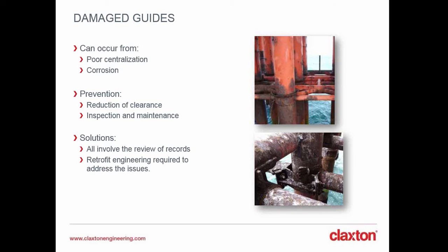So even if you try to minimize the overall ID, you might find yourself with a problem later on when it comes to designing a centralizer, because you will not have allowed sufficient space for a centralizer to be installed or a pre-installed centralizer to be run. So you just have to be a little bit careful with what you design, because you can also be limiting some of your options. This is typically addressed with the installation, during the drilling phase, of pre-installed centralizers. That will take up some of this gap.